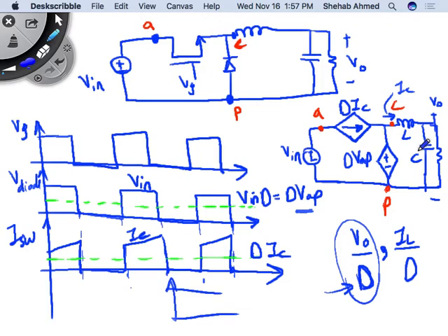You can play with the value of C now. Put this for any value of L and C. And when you simulate the transfer function, you have to put values, right? Come up with values and use some values in your textbook, that's good because then you can never be the same. Everybody chooses their own different value of L and C, and maybe compare a few values, and you will see that your choice of L and C, which affect your current ripple and your voltage ripple, is also affecting your dynamic response. Right? So do that. So this is for the buck converter.